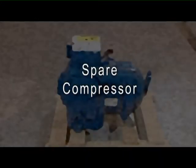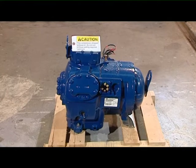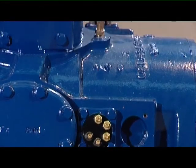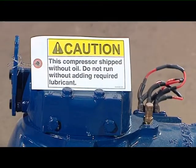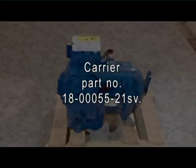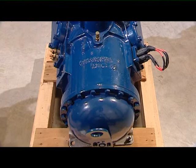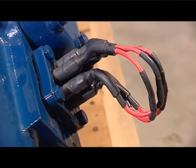Spare compressor. Only one compressor is supplied on board the vessels. The compressor is a dual voltage one. It has 2 terminals and is supplied without oil. The carrier part number is 18-00055-21SV. When possible, the compressor is supplied with the rear terminal bridged, so it can be used as a replacement